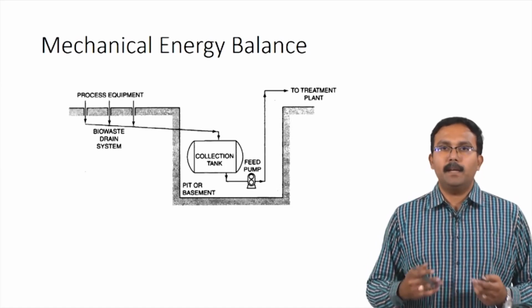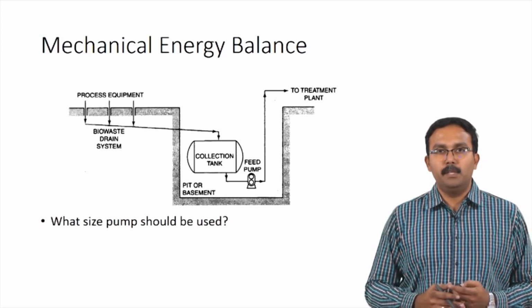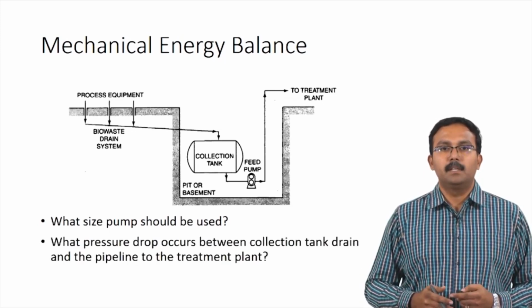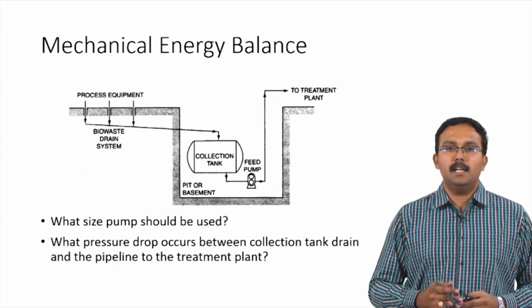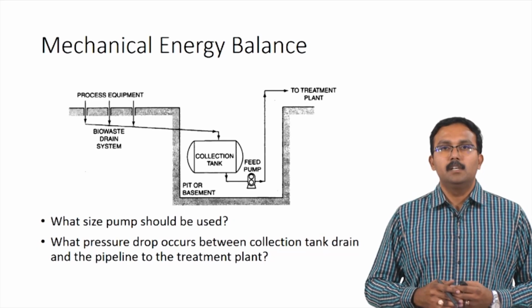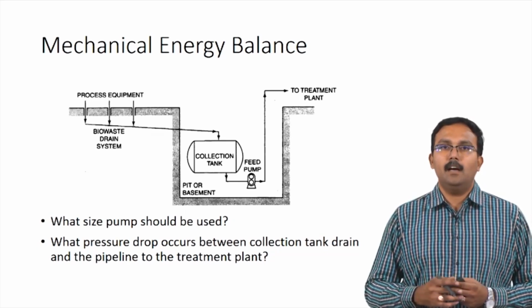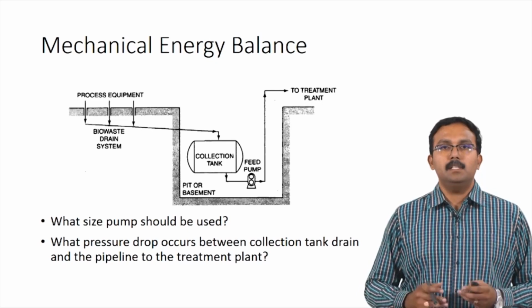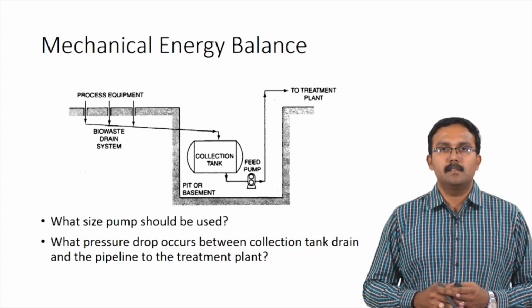You need to perform mechanical energy balances to calculate what size pump should be used, what should be the capacity of the pump, and what would be the pressure drop which occurs between the collection tank drain and the pipeline to the treatment plant. So, to understand and know these values is crucial for designing appropriate equipment. For this reason, we need to fully understand how to perform mechanical energy balances.